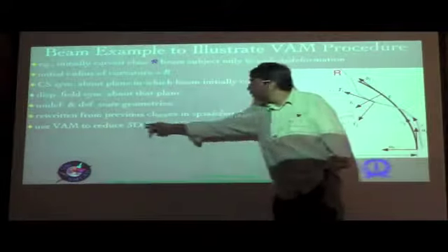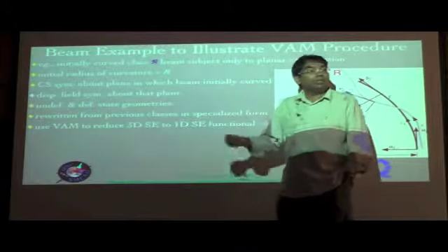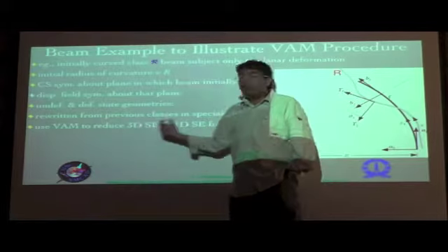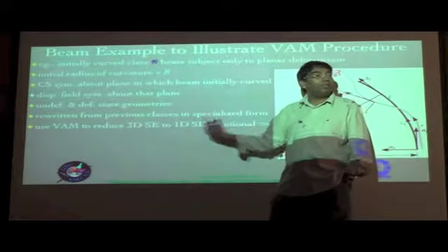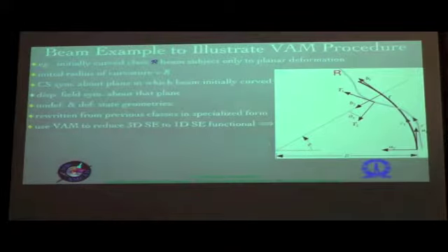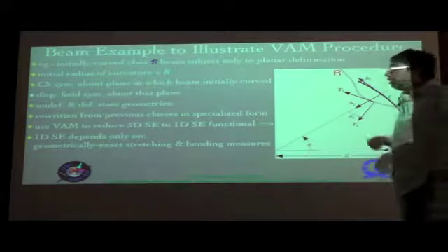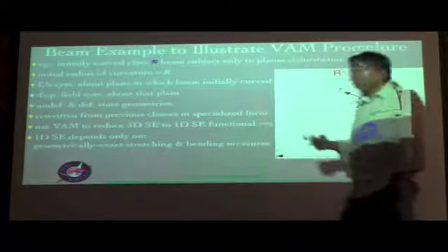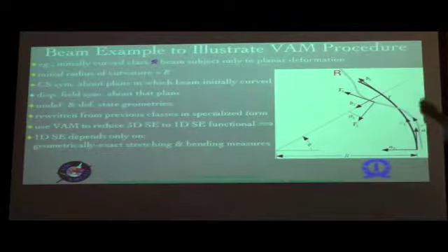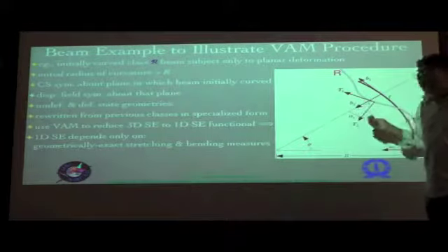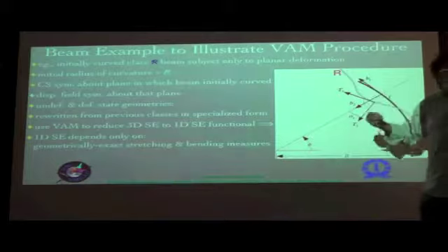So we are going to go from an energy which is described in the density form as energy per unit volume to something which is an energy per unit length of the reference curve. That is the goal. The 1D strain energy depends only on the geometrically exact stretching and bending measures. In general, there are four 1D strain quantities, gamma 11 bar and the three kappa i bars.